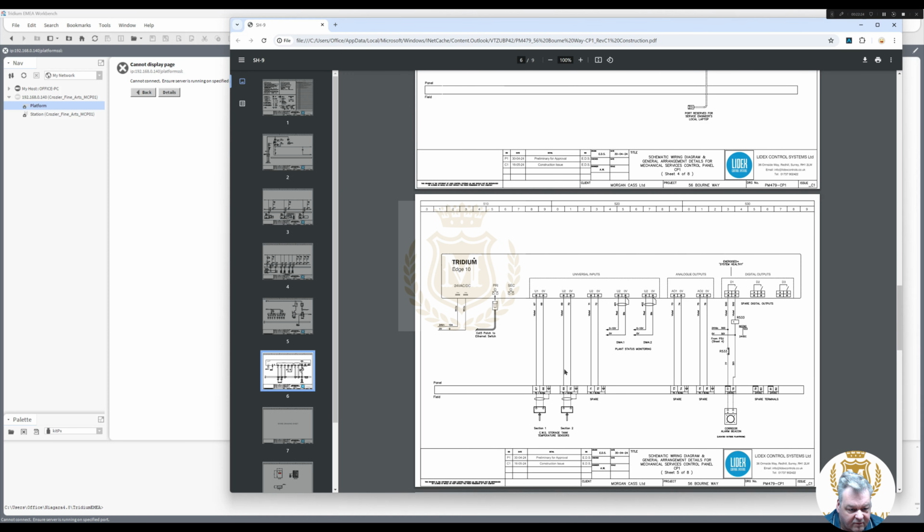Two temperature sensors, UI1, UI2, tank 1, tank 2, which we've explained. There are two DIM modules going in there, so that's using up UI2 there, that should be 3, that should be 4, that should be 5. But anyway, doesn't make any difference. The two analog outputs are not being used, and only one digital output's being used to send an alarm across.